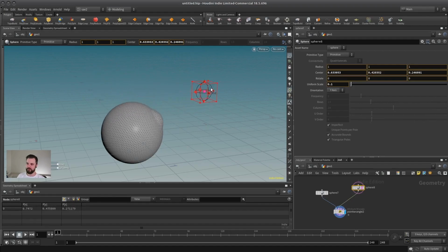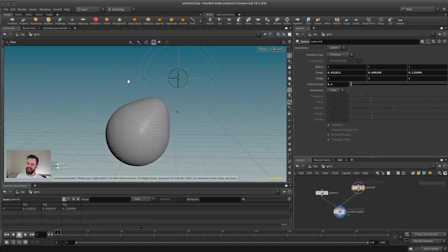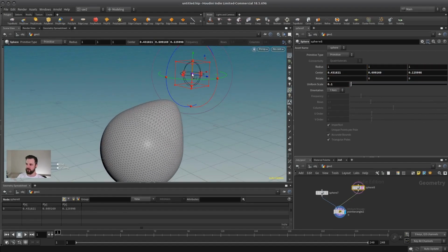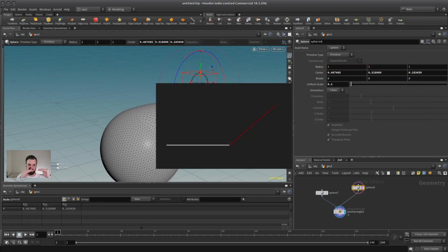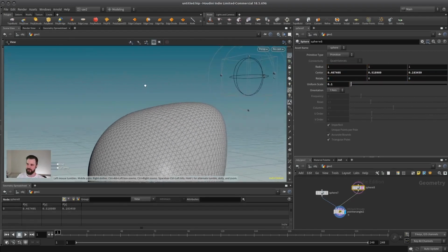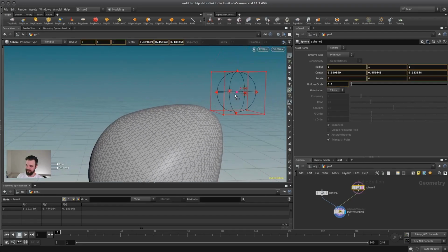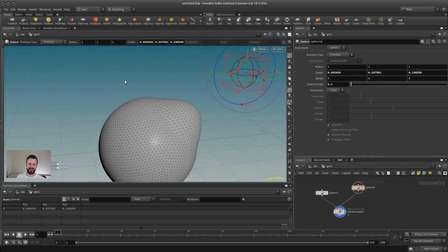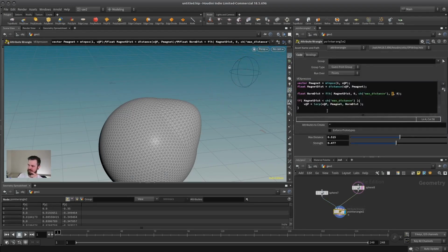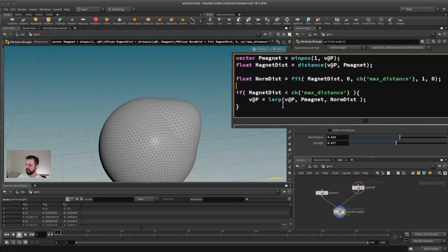Cool. Now, the only thing is, it's not super buttery smooth. You can see that here, the edge. Because it's a linear interpolation, it instantly goes up. If you look at a linear curve, it goes from 0 directly straight up, and this is what we see here, this little bit of a dent. Wouldn't it be nicer to have more of a rounded curve? Can we somehow build in a rounded curve in here? Well, what would be a rounded curve? A ramp. Oh yeah, right.